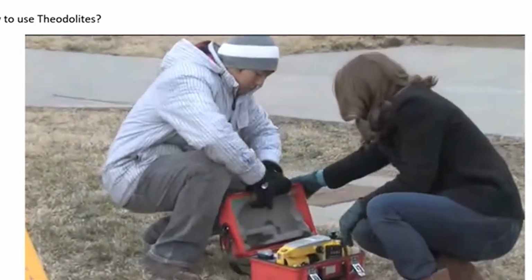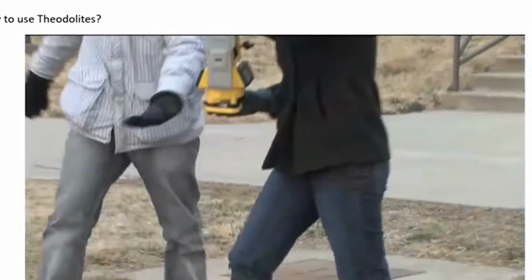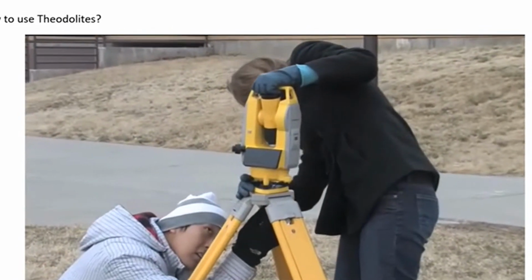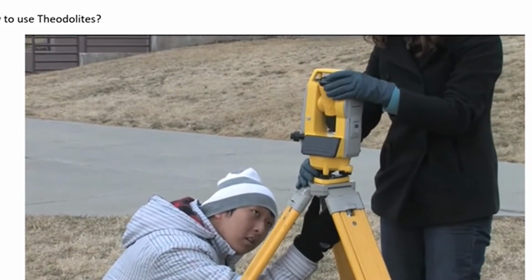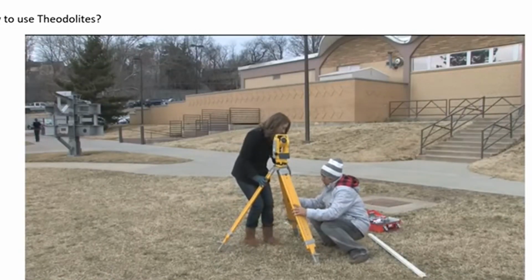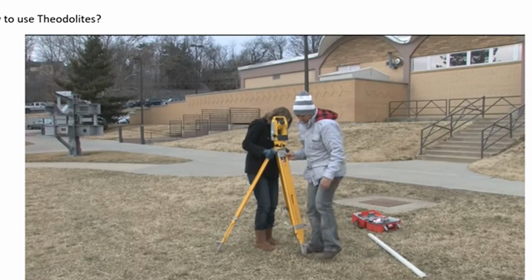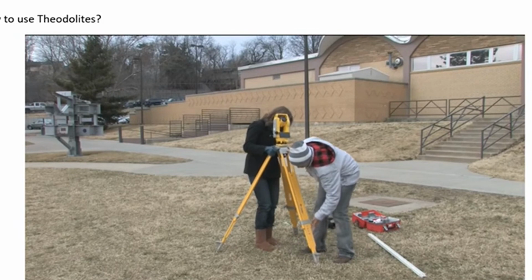The team then carefully removes the digital theodolite from the case and places it atop the tripod, securing the bolt firmly into the base of the instrument. The instrument should be at approximately eye level so that no one has to squat too low or stand on their tiptoes to be able to see through the instrument. Adjust the tripod height as necessary.